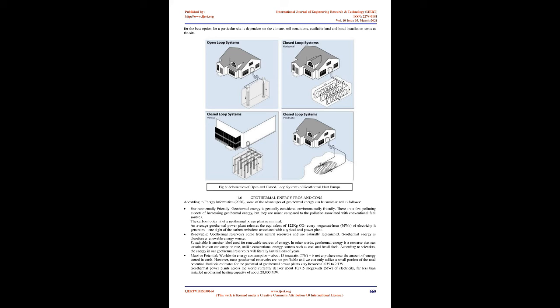The global average power output was 73% capacity factor of total installed capacity in 2005, but as much as 96% has been demonstrated. Great for heating and cooling. Water temperature of 150 C or greater is needed in order to effectively turn turbines and generate electricity with geothermal energy.